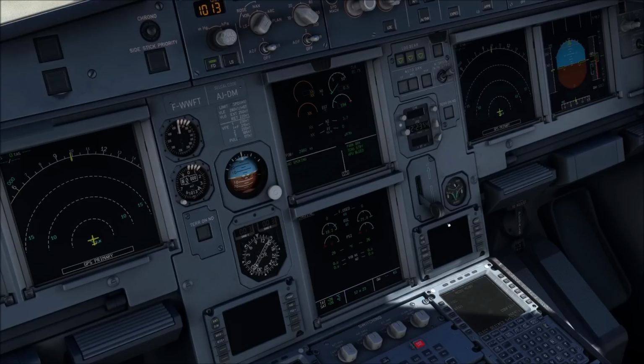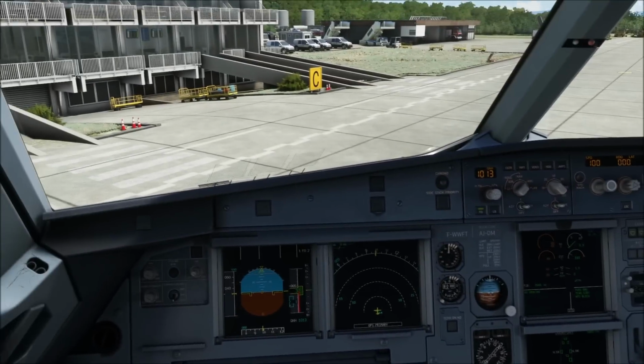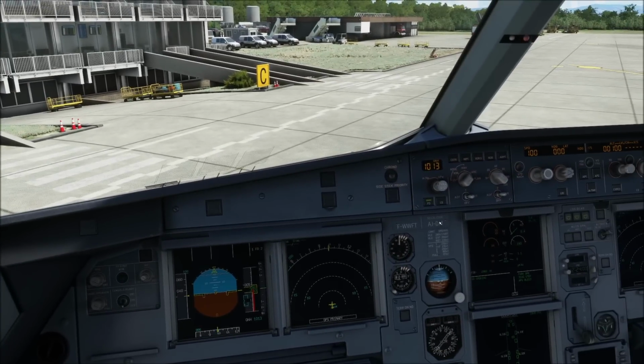So let's say that today we had to do a manual engine start, which is going to be way number 2 how to start an Airbus engine. Manual starting is recommended in case of an aborted engine start from the auto start because of engine stall, engine EGT overlimit, or low start air pressure.